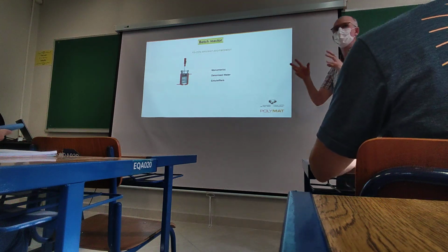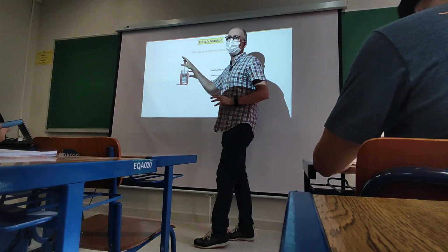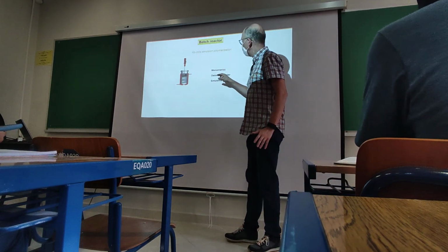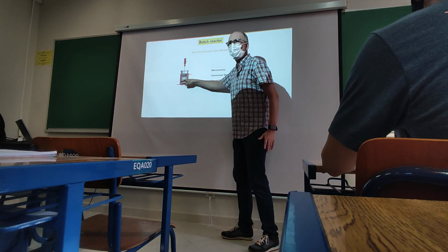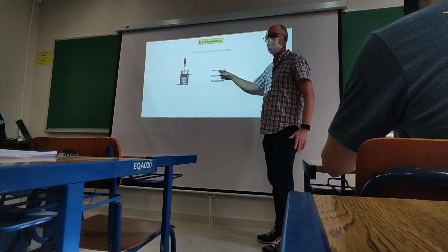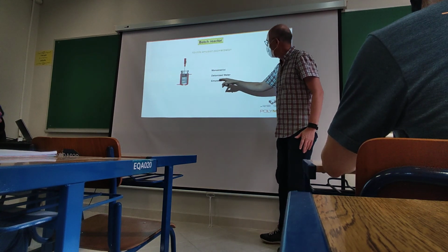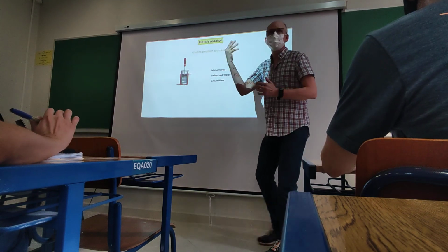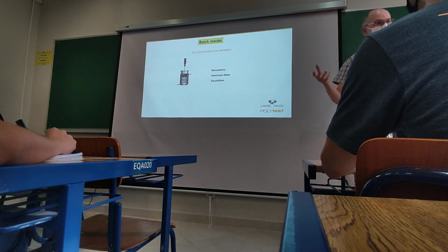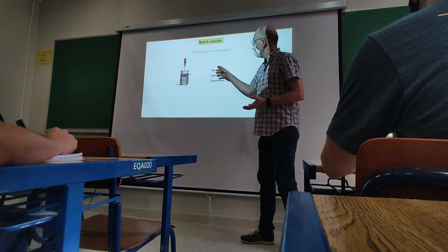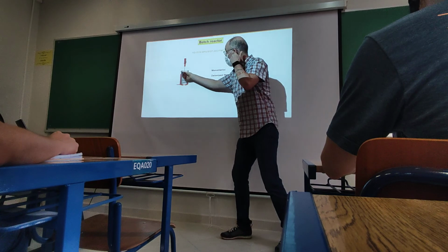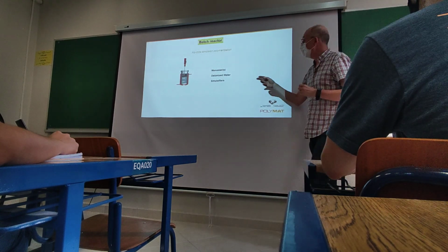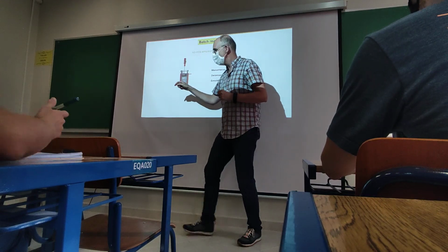Polymer particles occurs in a batch process. Okay? So the situation will be the following. We will introduce to a reactor the monomer, the water, and the surfactant, the emulsifier. Okay? We will use agitation to create a dispersion. Under this situation, we will heat the reactor until the desired temperature of reaction, and we will add an initiator.